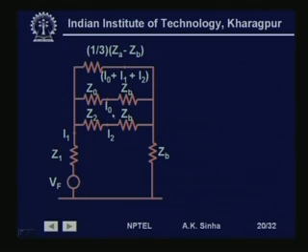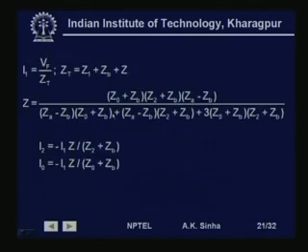So, we have this ratio coming into picture. So, Z by Z2 plus ZB and Z by Z0 plus ZB for I0, and for I2 we have Z by Z2 plus ZB part of the current I1 flowing. So, this is how we can calculate the positive, negative and 0 sequence current flowing into this system.